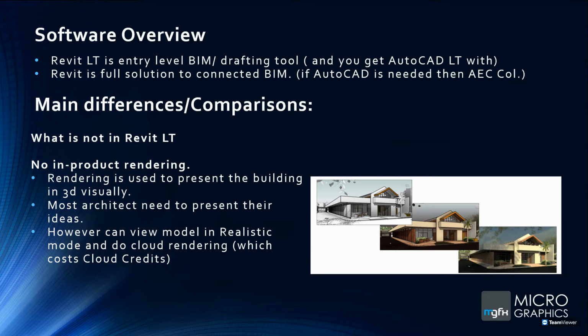However, in the LT you do have the ability to upload your Revit model to the cloud for cloud rendering purposes, meaning that you can still produce that third little image, but it's not local. Your model's been uploaded to the cloud, and it gets rendered on the Autodesk cloud service, or servers. Once it's done, you get an email back saying that your rendering is finished, and you can just visit the website and either download or re-render.